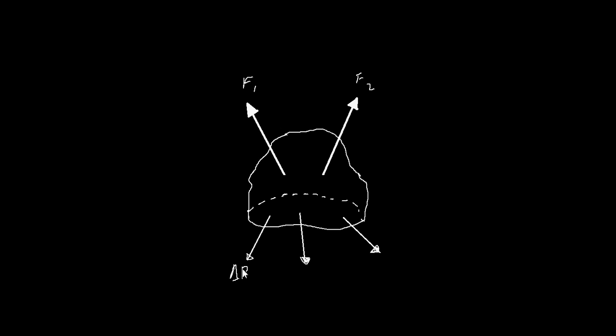Let's say delta P1, delta P2, delta P3. And these forces are developed in such a way that the body still remains in static equilibrium. In other words, the internal resistance developed within the body balances these applied forces. These forces are vectorial in nature and maintain the body in equilibrium under the applied forces. So they have a magnitude and a direction.